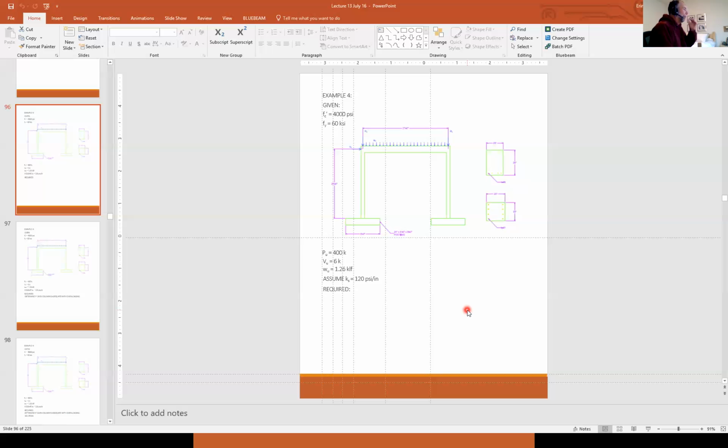So the prescriptive part of the code is very important, and I do hit on it a lot. As you know, I absolutely insist: do your minimum steel checks, your maximum steel checks, your beam width check, your phi Mn greater than Mu checks. I'm very strict about that because those are very important. But let's face it, the ACI code is like, what are we up to, 600 pages or so? The tests are not going to be so heavy on all these prescriptive things in the code.